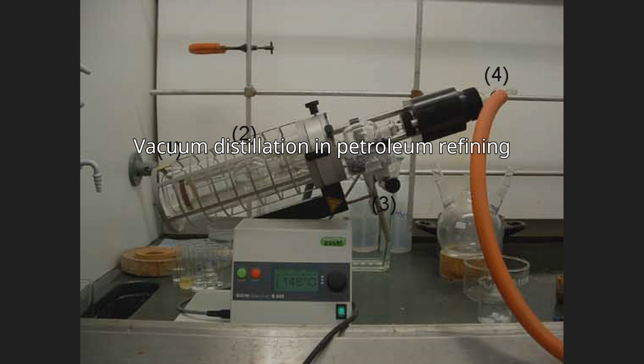Distillation columns, such as those in images 1 and 2, may have diameters of 15 meters or more, heights ranging up to about 50 meters, and feed rates ranging up to about 25,400 cubic meters per day, 160,000 barrels per day. The vacuum distillation column internals must provide good vapor-liquid contacting while, at the same time, maintaining a very low pressure increase from the top of the column to the bottom.